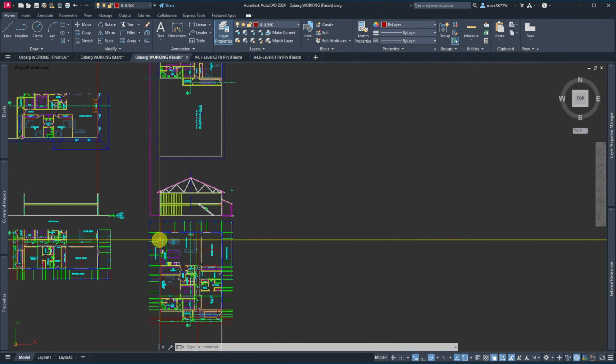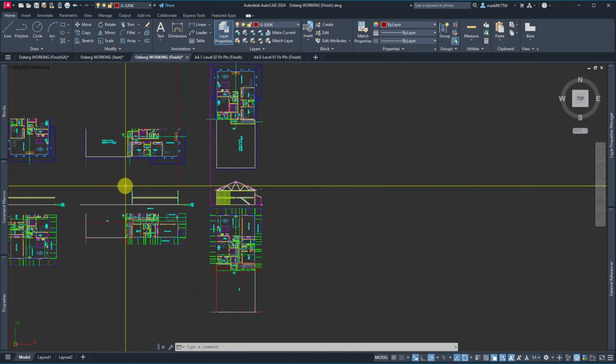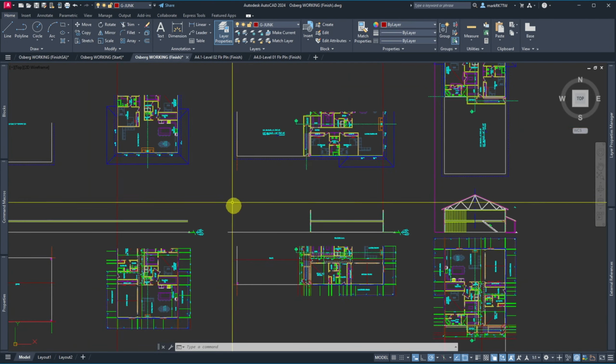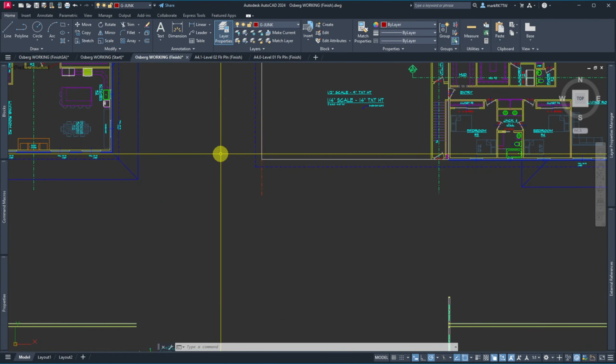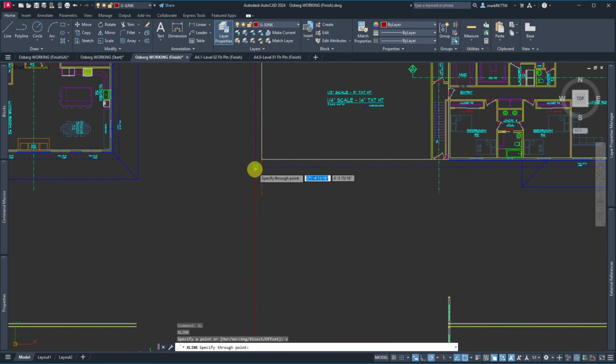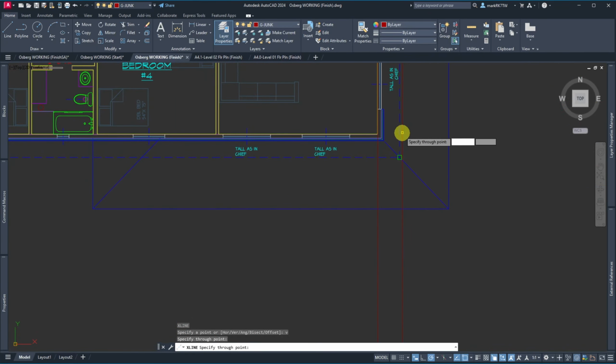But what I wanted to do with the rest of this lesson was just show you how to get these lines over to here. So this building actually extends way out. And so I'm going to X line vertically, place on the edge of where that roof's supposed to terminate, and on the top level where it's supposed to terminate here, the solid line is the roof below.